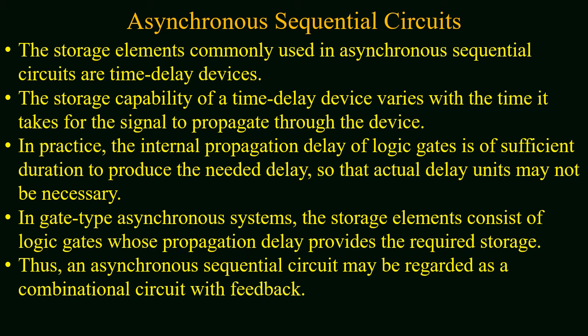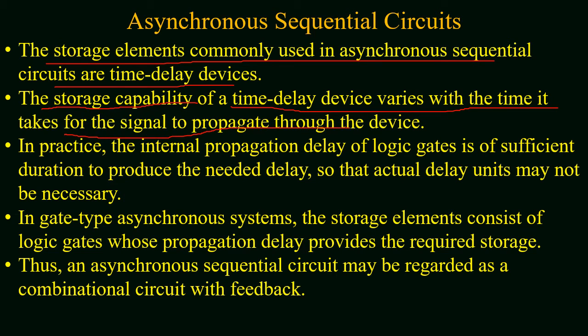Now we will study about asynchronous sequential circuits. The storage elements commonly used in asynchronous sequential circuits are the time delay devices. The storage capability of a time delay device varies with the time it takes for the signal to propagate through the device. In practice, the propagation delay of a logic gate is of sufficient duration to produce the required delay.